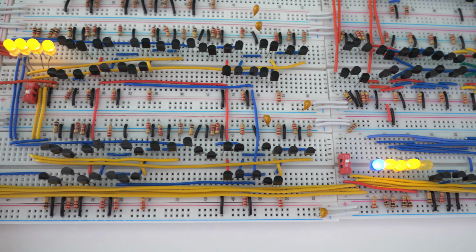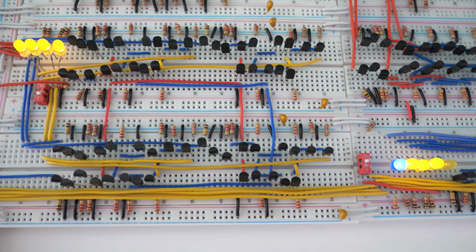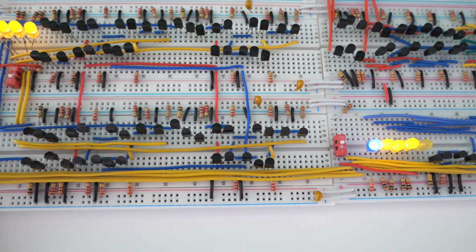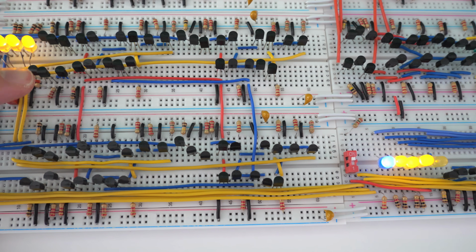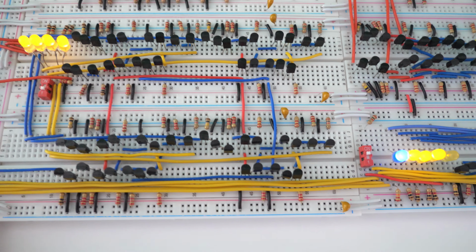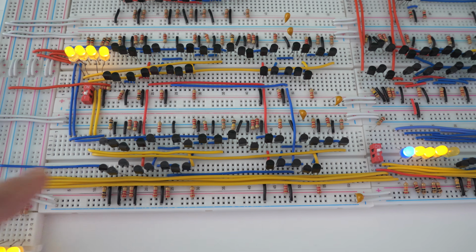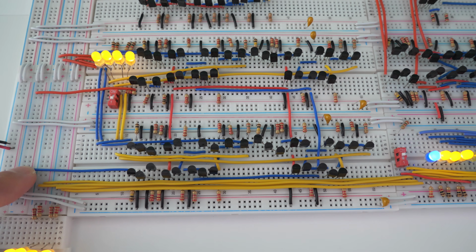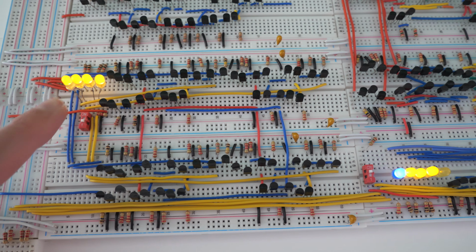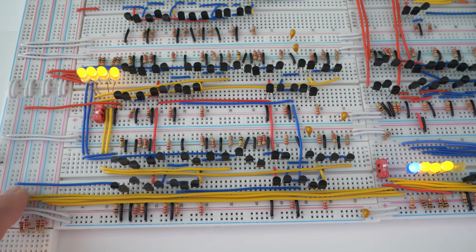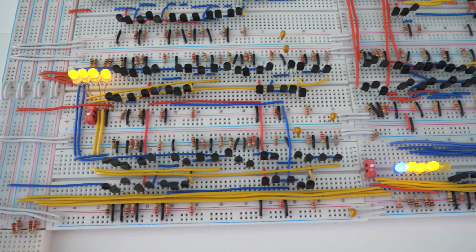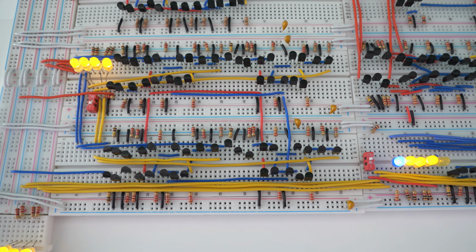And then at the left side of this register, we have some buffers. This is the clock gate, which is actually just an AND gate. And then we have another buffer right here, which is connected to the clear pin on our data bus. So if we want to reset this to 0, all we have to do is ground this value, and our output register will be cleared to 0.